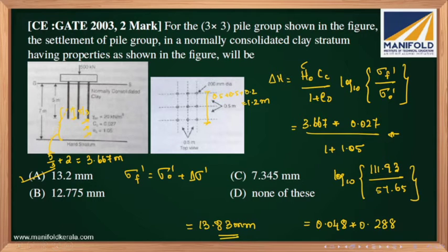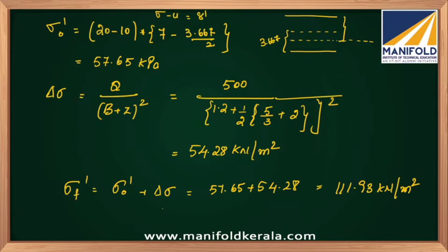So here the only thing you want to remember is, if it is a friction pile, the load distribution is happening from L by 3 from the base of the pile. So this point alone you want to remember. To solve this type of question, apart from this, all other things are very basic. Nothing to worry about with respect to this question. So now let's move to the next question.